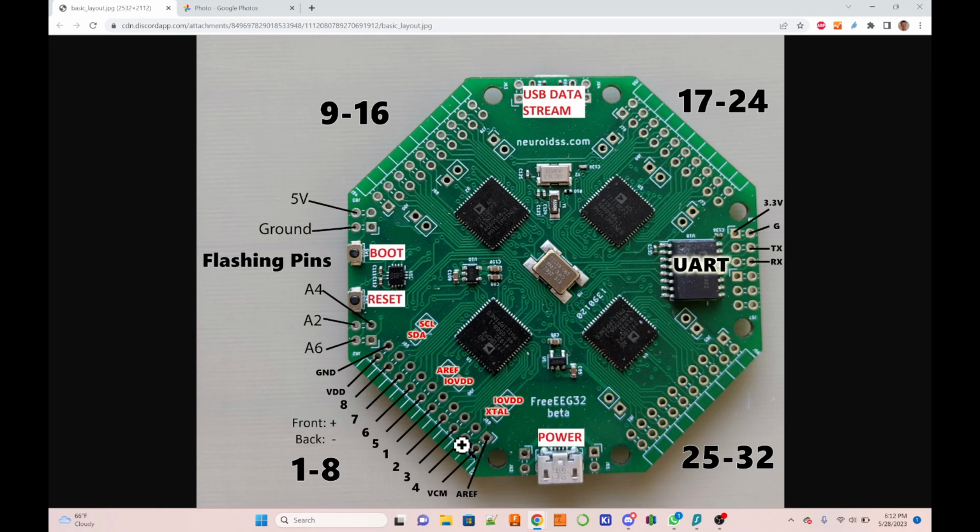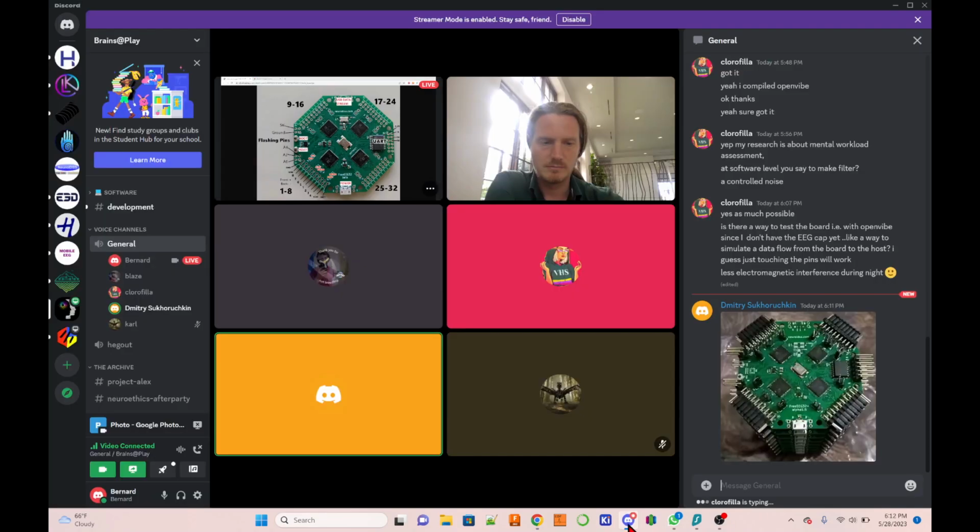And then when you touch that pin, there will be something, but not much noise. And if you touch the pins which are not connected to anything, you'll see a big spike. I sent an image of 8 boards interconnected, where I tested noise with jumpers. Oh yeah, I can see them.